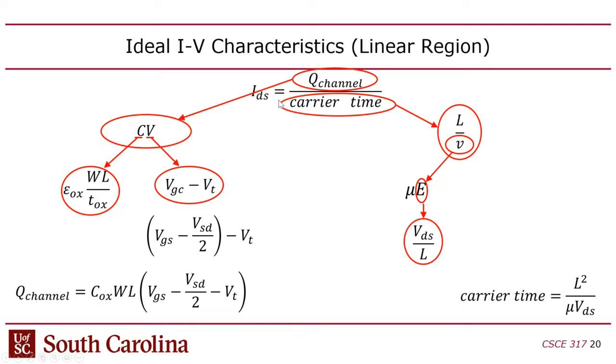I mean, assuming that you're using minimal sized transistors, which means that you can fit more transistors on the chip, obviously, but for each individual transistor, the current stays the same. Now you might say, oh, wait a second, then that means the whole chip is going to take more power, though, because you're adding more transistors to the chip. And that's true. That wasn't always true. So there's this thing called Dennard scaling that basically said that the total amount of power per unit area of a chip is constant even as you scale down. And you might say, well, how is that possible if you're going to have more transistors and each transistor uses the same amount of power as the ones before?